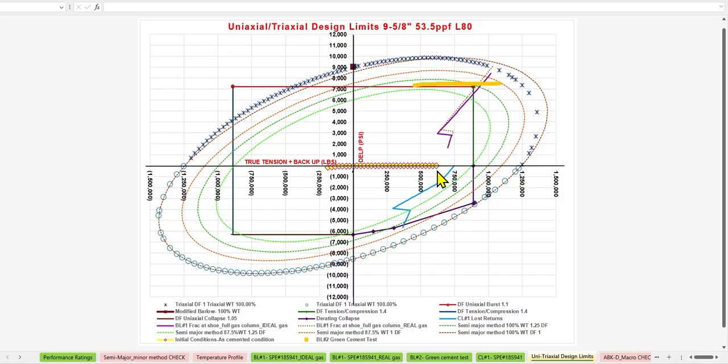And also there is a thermal effect, and also additional surface pressure of 9200 psi from this point to this point. It can give you an idea of how much additional tension you have added into the casing from an initial condition, basically the as-cemented profile, to a load case of frac at shoe, gas to surface, including thermal and ballooning effects.